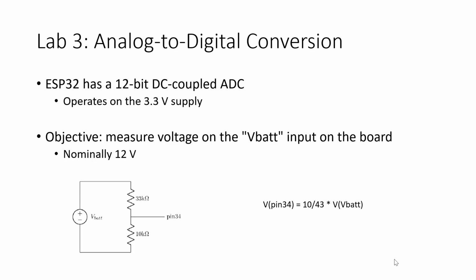Okay, but there was a bit of an oversight here, because right next to the VBAT terminal is something called V 5 volt DC. And the 5 volt DC is shorted to the 5 volt supply on the ESP32, which is probably also shorted to your computer through the USB connection, I'm guessing, right? Which means that if you misplace the alligator clip by 2 millimeters or so, you'll cook not only the board, but possibly the computer as well. So you want to be careful with that.